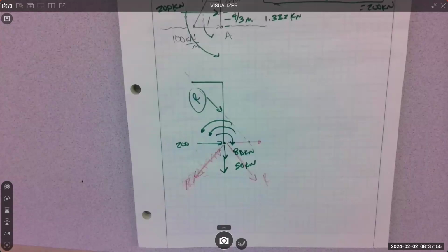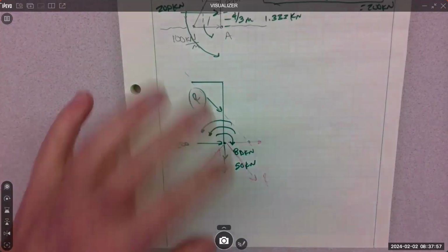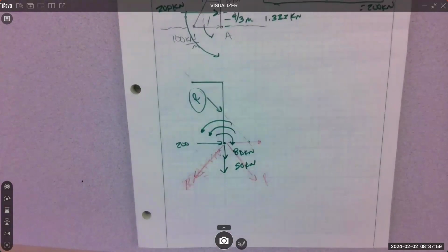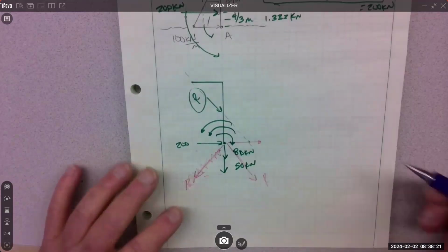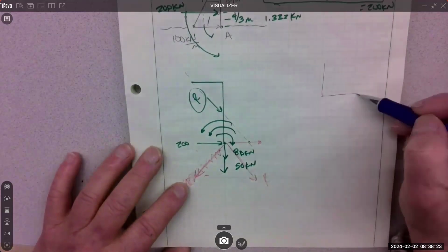Yeah, okay. So what's different is you do this on the telephone pole problem. I think I mentioned that the other day, that we want the resultant to be down through the concrete. So the resultants on telephone poles, we want them pretty damn vertical. They can move a little, but they need to intersect the concrete down below. That indicates stability. Okay. The other thing we do this all the time on is gravity dams.